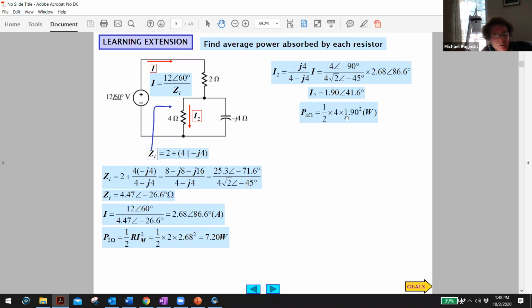I'll see people get this value right here, I, and they'll have it in a real and imaginary portion. Do y'all follow me? Now listen to me carefully. They'll have a real and imaginary portion. Then they'll square that. Now take the magnitude and square that, and they'll get the wrong answer. Do you hear me? If you have 1 plus J1 and you square it, what do you get?